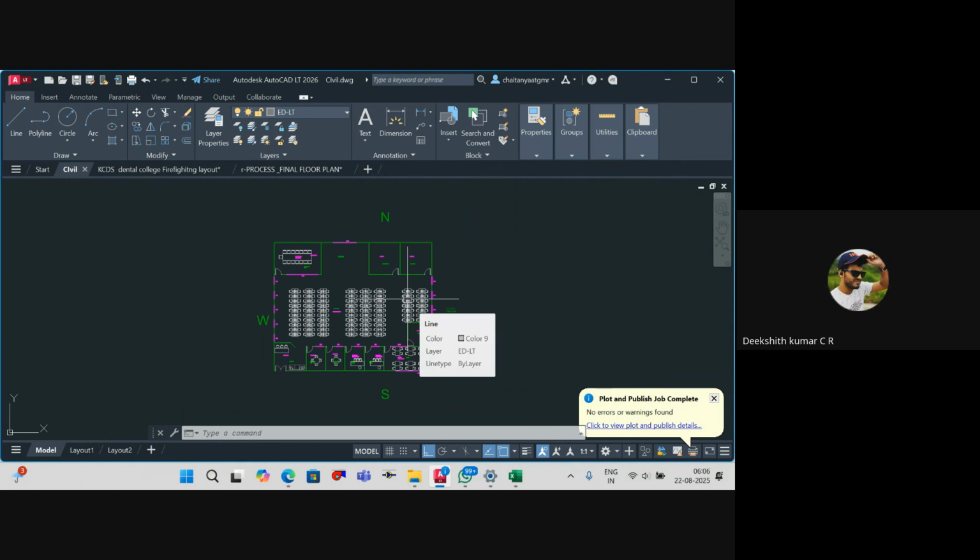You agree? So if your building is made with brickwork, don't you think it will resist for a certain time? The minute you have heat, does the temperature come into your room space immediately? Don't you think it will hold heat for some time? The block work, whatever you constructed with, when the photons hit the surface, it gets localized and heated up, and it will take some time to dissipate into your room. Yes, it will. That will approximately be 1 to 2 hours, because 2 to 3 you have the highest sun.